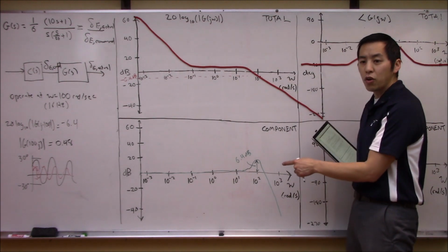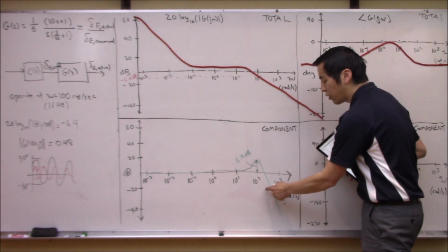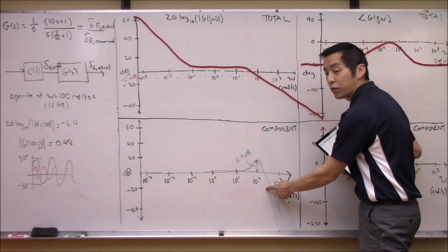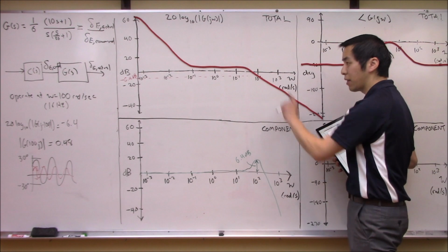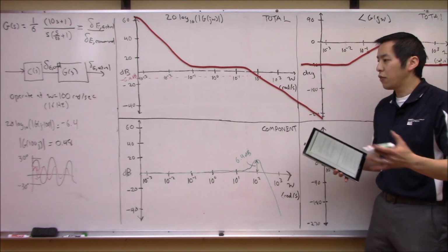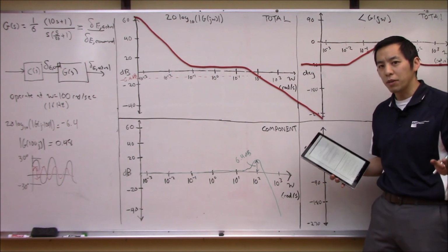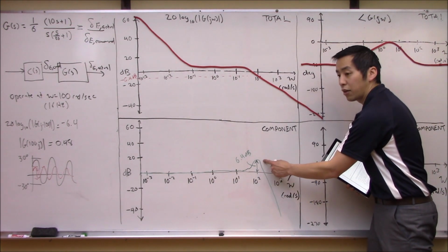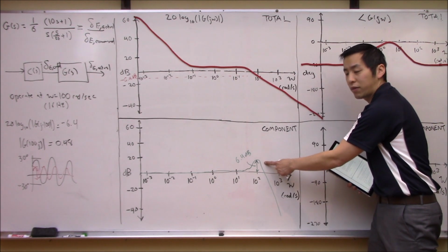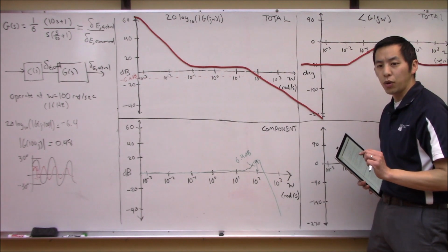So the other way, we can go around this sort of backwards and say, here is the component I need to add. This is the frequency response of the component I need to add. What type of transfer function will get me that? Well, again, luckily, if you watched our previous discussion, we saw that this looks a lot like a pair of complex conjugate poles. A pair of complex conjugate poles with some damping ratio between 0 and 0.707 will get you this hump, and we can place this hump exactly where we want it to.